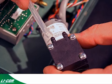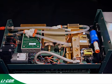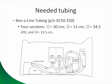You will want to remove tubes 2, 3, and 4 from the system, and your instrument should look like this at this point. You're going to have some tubes still in place, but you have removed the 4 tubes to alter the flow path. We're now ready to begin installing the modified plumbing. You're going to need 4 new tubes to replace the ones that you've just removed. The lengths are listed here.